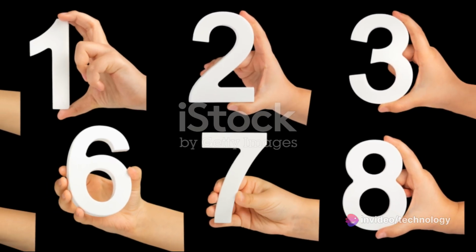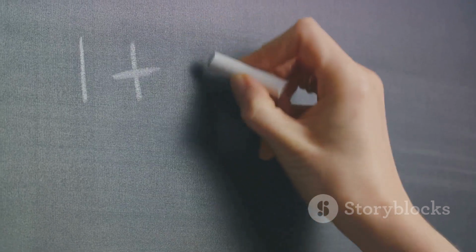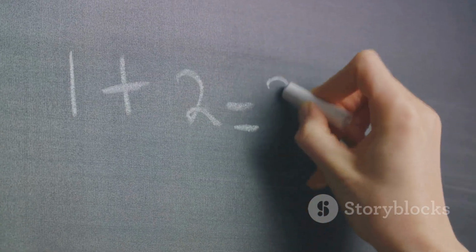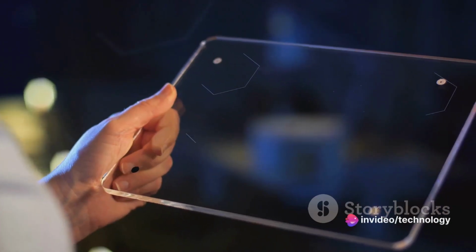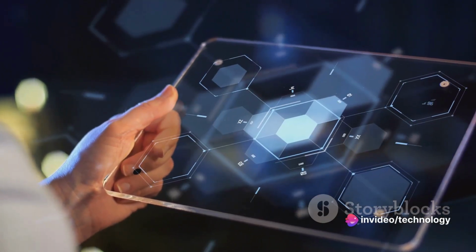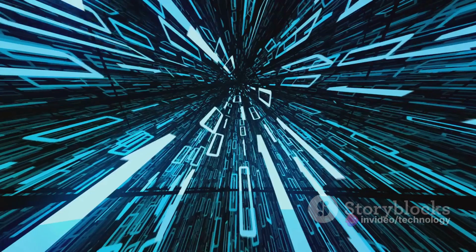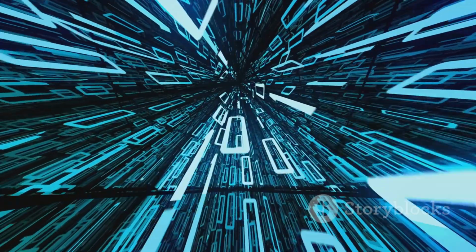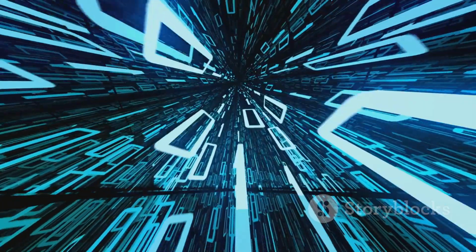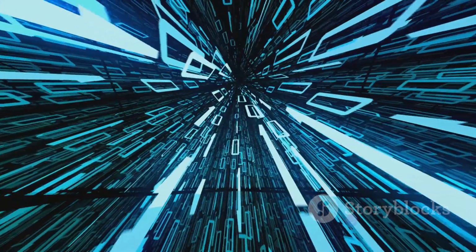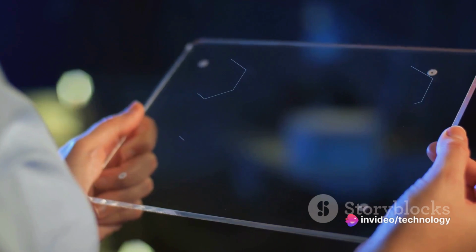Here's how it works. For the first combination 0, 0, both parts of our Boolean expression are 0 because anything multiplied by 0 is 0. Hence, the output is 0. For the second combination 0, 1, the first part of our expression is 0 because A is 0, but the second part is 1 because we are multiplying 0, which is the negation of A, with 1, which is B. Therefore, the output is 1.